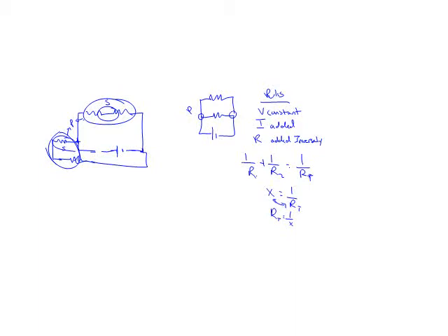All right, resistors in parallel. We're going to combine together the resistances first to find the total resistance. So that's adding up your resistors inversely. Then you will find the total current, usually because you'll be given voltage, using V equals IR. Once you know V, V is constant. It'll be through the whole thing. You can solve V equals IR for each current to solve for the missing I, and then P equals IV to solve for the missing P. Add up your P's and make sure they equal the total P to double check.